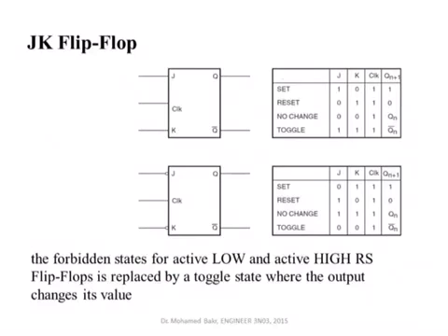In the reset condition, you put J equal to 0 and K equal to 1. In that case, the output Q will be 0 and Q bar will be 1. Okay, so you can see here the next state, and here I'm not showing Q bar, I'm only showing the new state of Q. This will be reset. Now, as in the previous case, this one here is an active high. If I put 0 and 0, it means do not change.